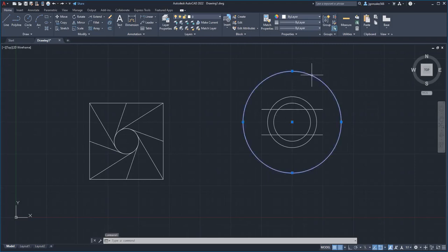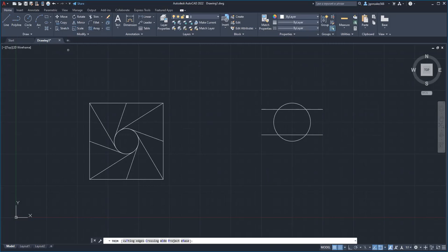Let me get rid of these guys now. I only want the original. Just make a circle with 2 lines through it. Try to make it symmetrical slices like this. Same location, same sizes. The exact spot doesn't matter, but something like this is good. Ready? Let's do the trim command. So trim we've talked about already. So I'm going to trim all the stuff that's sticking out just for this example. So everything out here, you get rid of it.